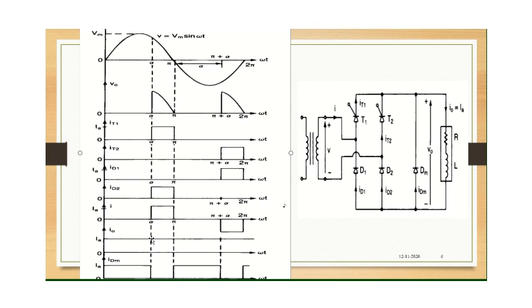So here when the thyristor is conducting, the current will be gradually increasing, and in this period between pi to pi plus alpha, it will be slowly decreasing because of the inductive load. Again from pi plus alpha when T2 is triggered, the current again will gradually increase. So the energy is slowly stored up in the load, right? So the current is slowly building up. So it is a variation, increasing, decreasing, increasing, decreasing in this fashion.